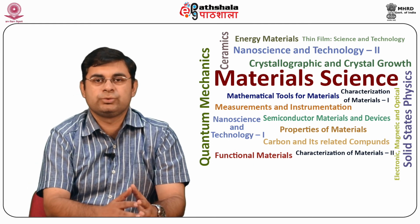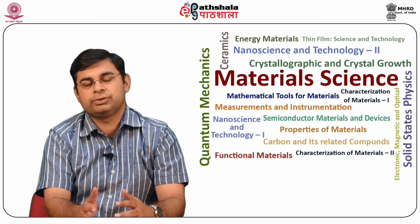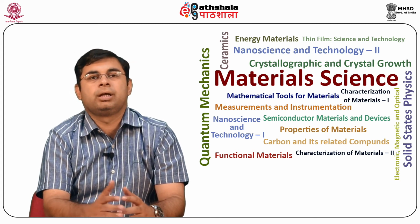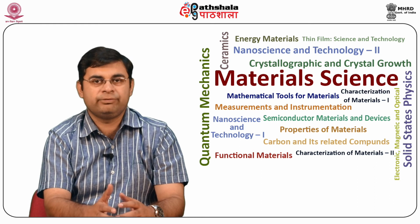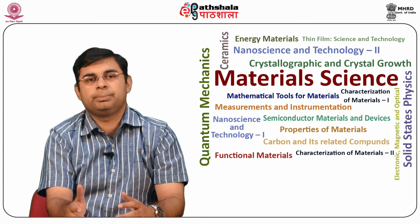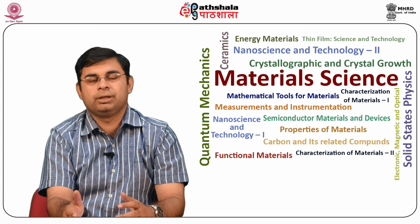In such a transducer, a conducting plate is kept near the coils carrying alternating current, and eddy current is induced in the conducting plate. This plate produces its own magnetic field in opposition to the magnetic field created by the coil. Thus, the currents induced in the plate reduce the net flux associated with the coil.